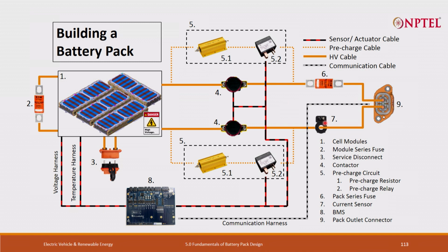You may require different sensing devices: temperature, voltage, Hall sensors. Connect all those things, the pre-charge circuit, to the service outlet, and then finally put it in one casing and start testing. Now if everything is satisfied, you have several other constraints: packaging, weight, energy.